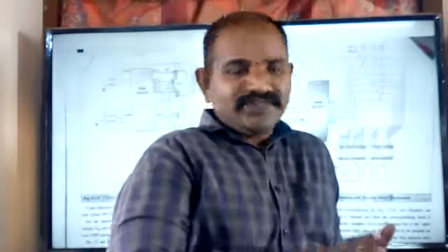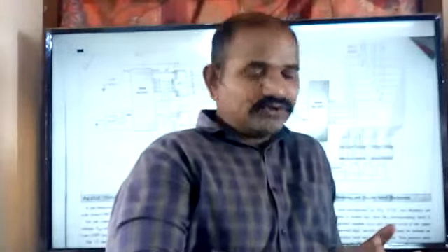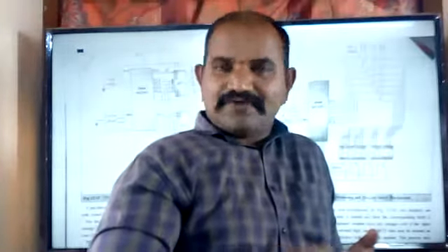So in short, when to use a 7-segment display? If there is no power restriction and you would like to display information that is only numerical values on the screen for long viewers, then you are supposed to go with the 7-segment display. If there is a power restriction, then you can't go with the 7-segment display; you are supposed to go with the LCD display.